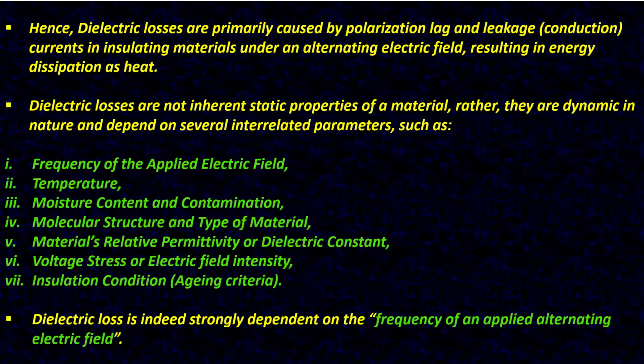Hence, dielectric losses are primarily caused by polarization lag and leakage current, that is, conduction current in insulating materials under an alternating electric field, resulting in energy dissipation as heat. Dielectric losses are not inherent static properties of a material. Rather, they are dynamic in nature and depend on several